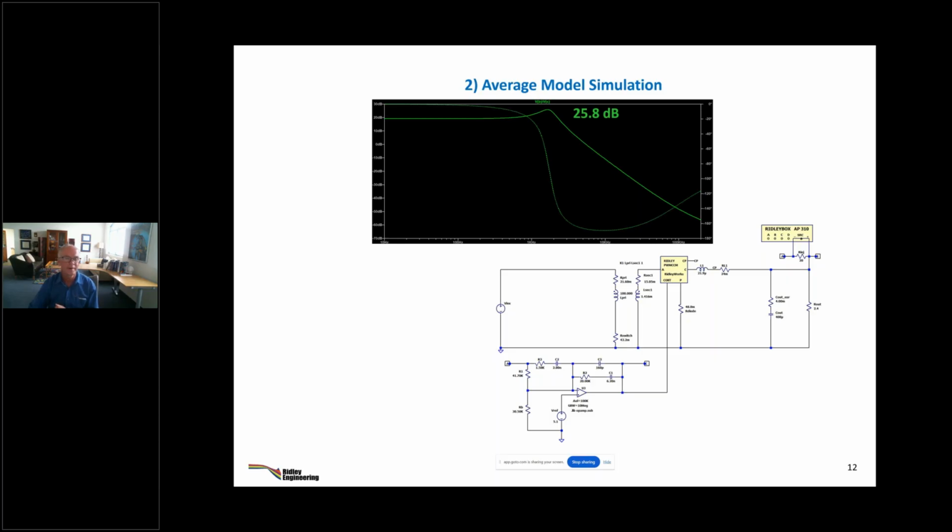And again, you need to know how to build this circuit, and beware once you go digging into this, and again, this will drive you nuts, that there are so many different average circuit models. When Vorperian did his work, in a sensible world, everybody said, hey, that's great, let's all do it that way. But the world doesn't work that way. Everybody wants to do their own average circuit model. So you've got to pick and choose amongst a dozen of those to see which one works for you. So that's complication in your life that you don't really need.